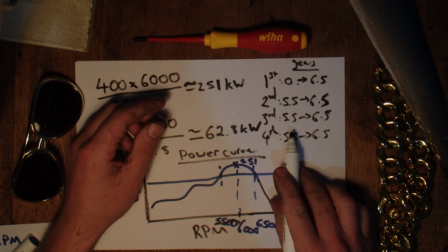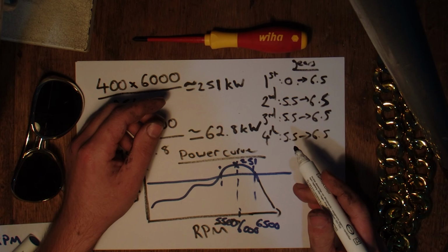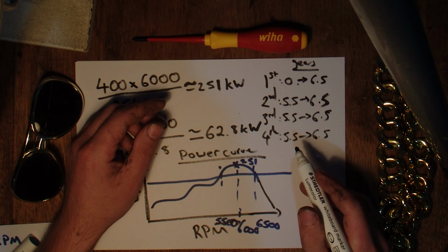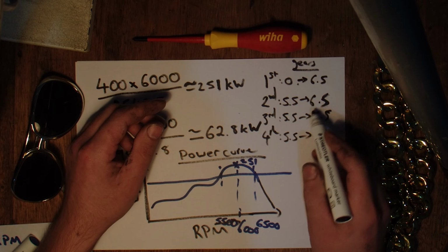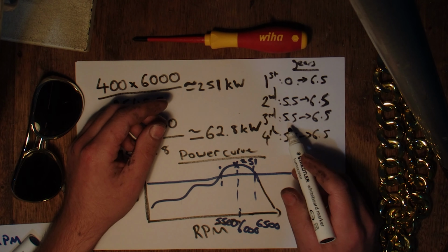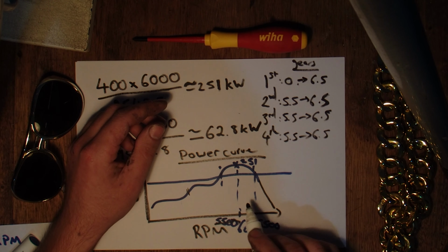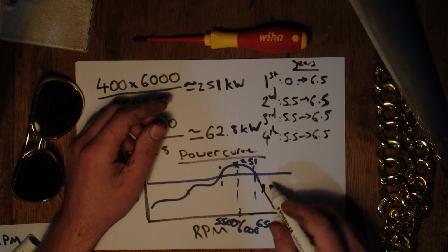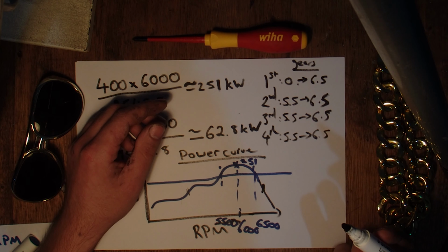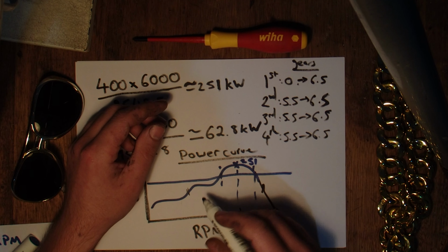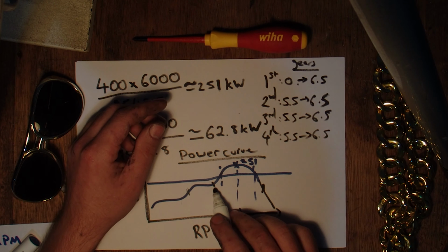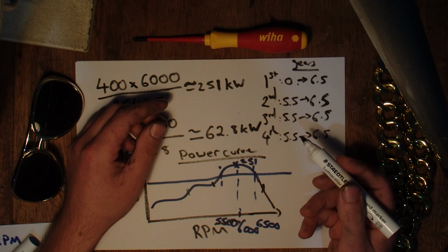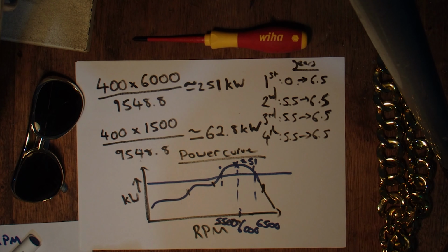And if your gears don't line up perfectly with this, then let's say your second to third leaves you going from 6,500 RPM back to 4 or something like that. Well, if you're going to end up over here, then you might want to over rev a little bit. You want to take it a bit further past because that's basically the same thing. And then when you change gears, you back up into here, and it's not going to bog down as much. You're back onto the power quicker. But ideally, you pick your gear ratios and then be able to do whatever you want.